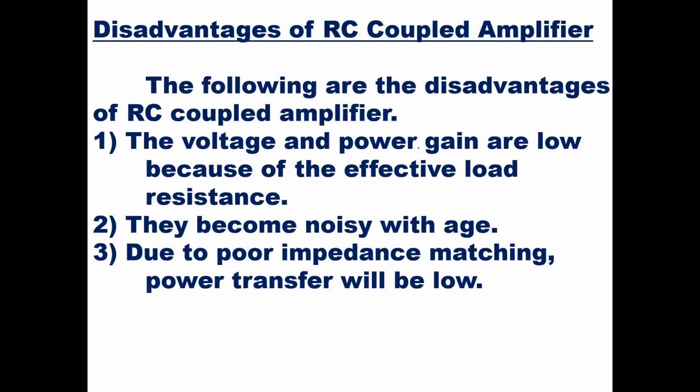Similarly, we'll go to see the disadvantages of RC coupled amplifier. The following are the disadvantages. Number one, the voltage and power gain are low because of the effective load resistance. Number two, they become noisy with age. And number three, due to poor impedance matching, power transfer will be low. So these are the disadvantages of RC coupled amplifier.